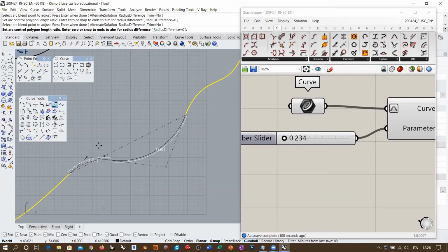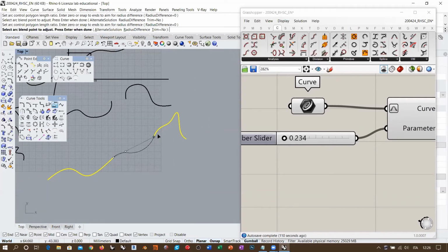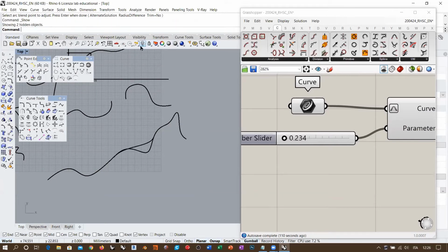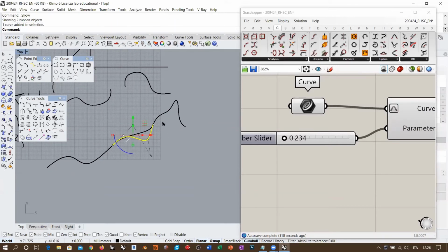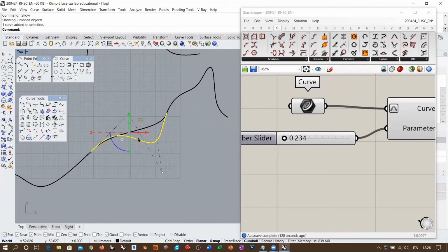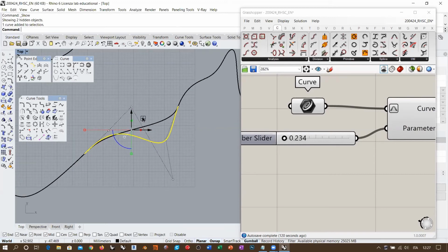Because this is very easy. You know that you can only pick the center point here and the center point here and trace this arc and this arc, okay? So this is good for production, whatever type of production you are into, okay? While this one is extremely nicer in terms of geometrical aspect, but it's more difficult to construct. Of course, you can also approximate this blend curve with a degree 2 curve. You have some deformation occurring, of course, but in the end, you will get a curve which is more easy to represent in real life.